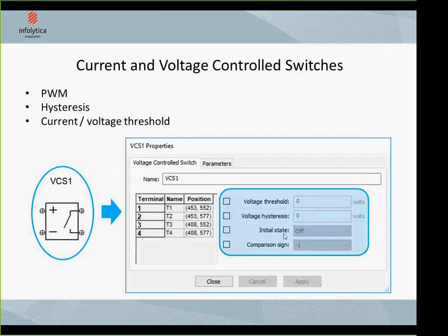This is in addition to other circuits. It does not mean previously we did not have switches; we had switches, like position control switches and other switches. But the key difference is you had to know when to transition or activate the switch. In this case, you don't have to know. You can use the current or the voltage in the circuit to effect your switching transition, which basically means you can feed back and do it within the circuit, and all that is within MagNet.